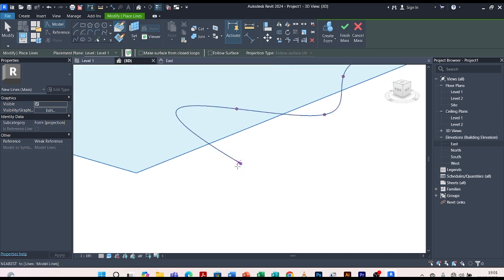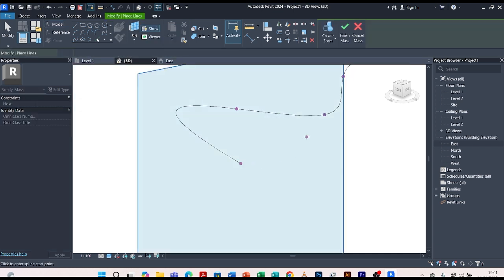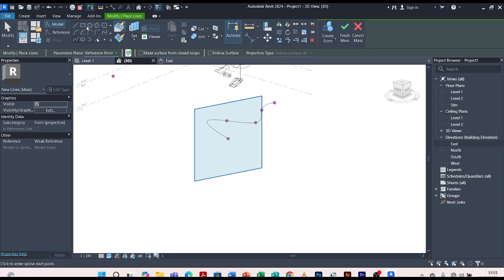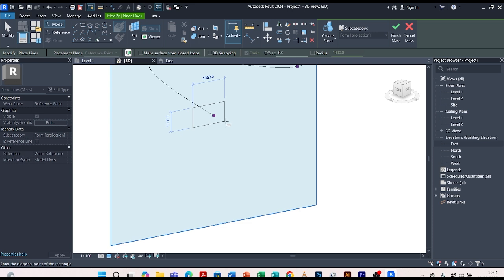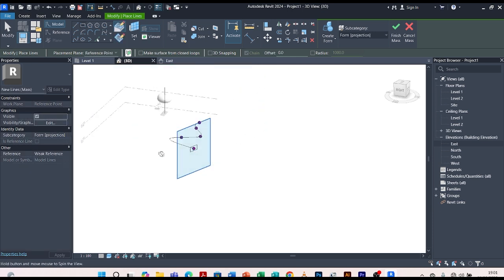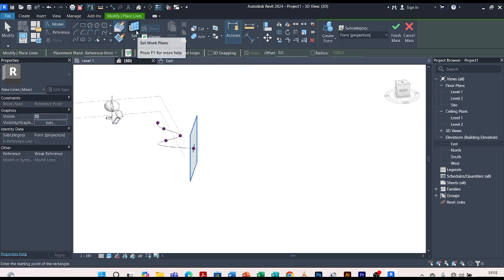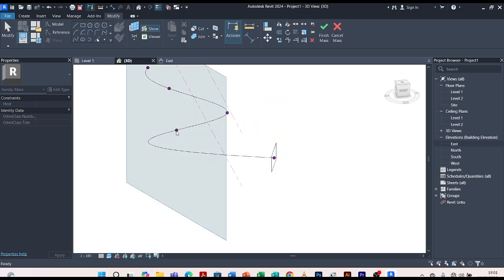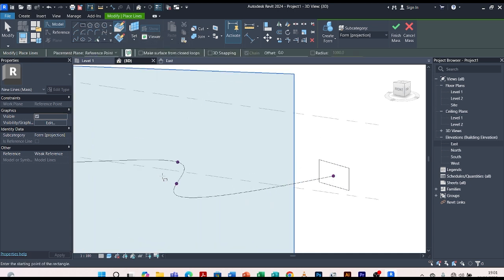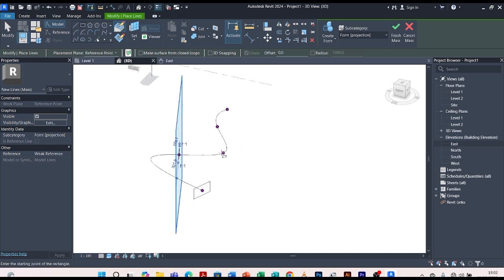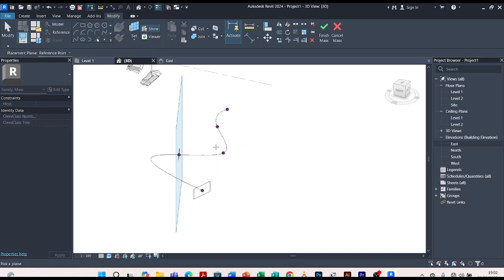So I have to create my work planes, or my reference planes at these nodes. So I'll come to set a plane. I click on that. Then let me use this shape of a rectangle. Simply come, click on that, then have maybe my first rectangle like that. Then I come back, set a plane. I'll set it at this node, and I come create another shape like that. Then let me set also another plane there.